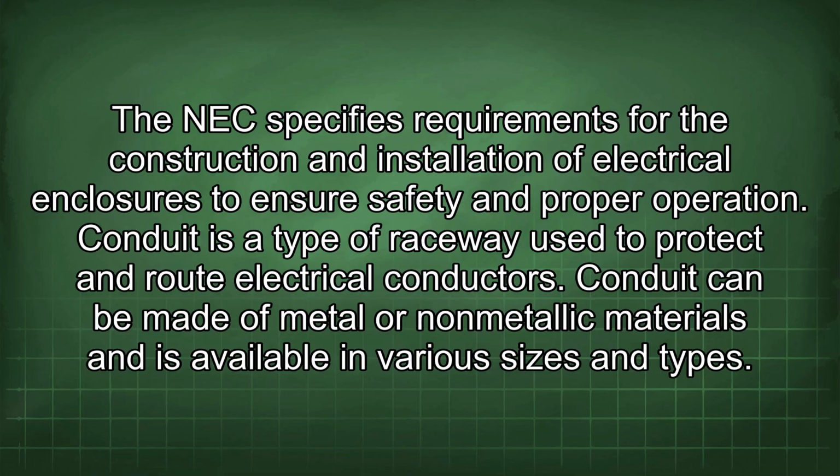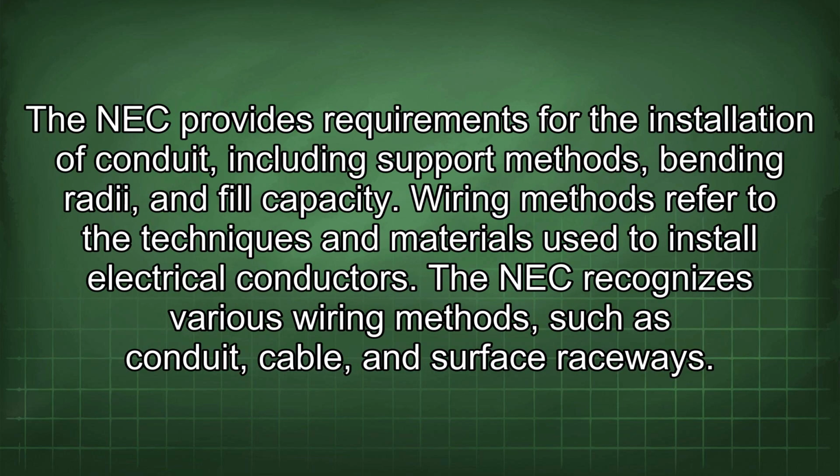Conduit is a type of raceway used to protect and route electrical conductors. Conduit can be made of metal or non-metallic materials and is available in various sizes and types. The NEC provides requirements for the installation of conduit, including support methods, bending radii, and fill capacity.